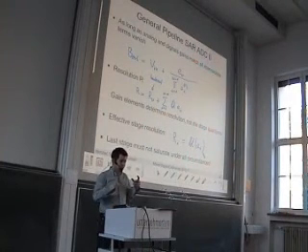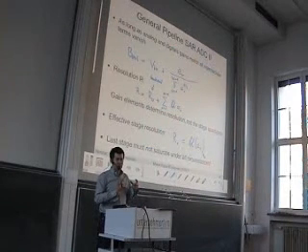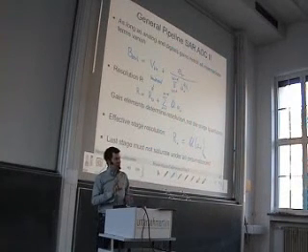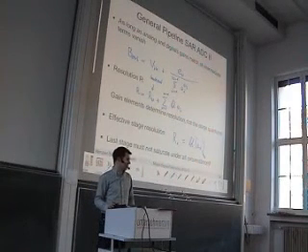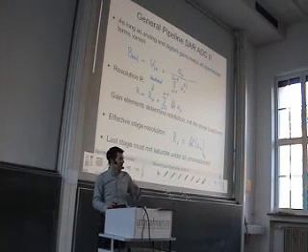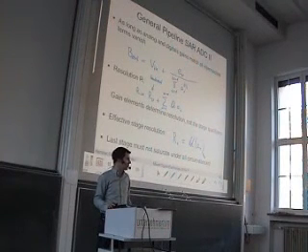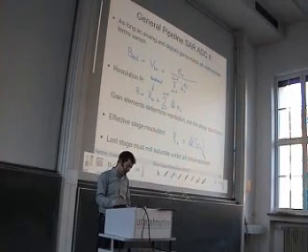And say, okay, we have implemented the chip. Now there is a certain gain. We have to measure it and adjust the digital gain to this measurement. And this measuring and adjusting, this is what people call a calibration required for the pipeline ADC.